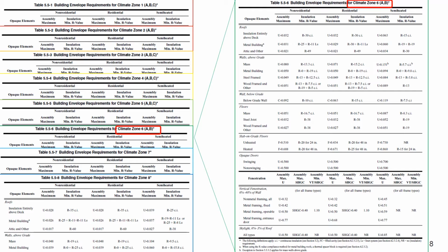Notice the semi-heated space columns. Residential aligns with or is equivalent to the IECC, where it talks about Group R, so sleeping spaces within commercial building occupancies, and then the non-residential, so outside of Group R, or outside of the residential, I should say, as defined in 90.1.